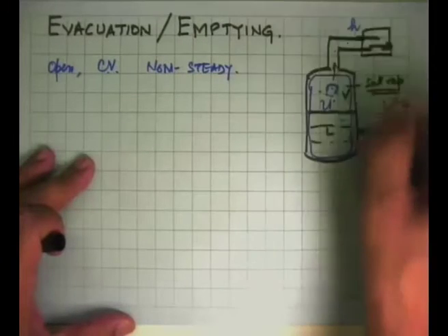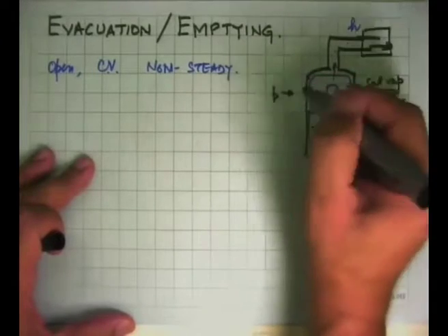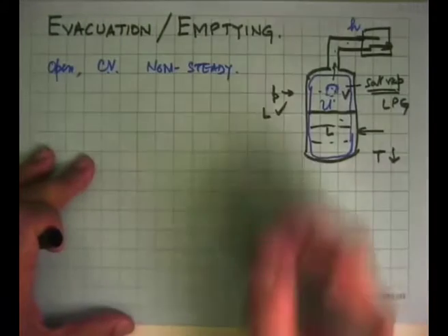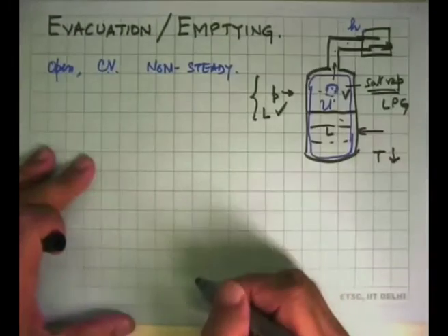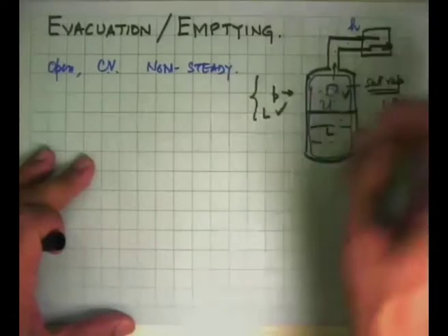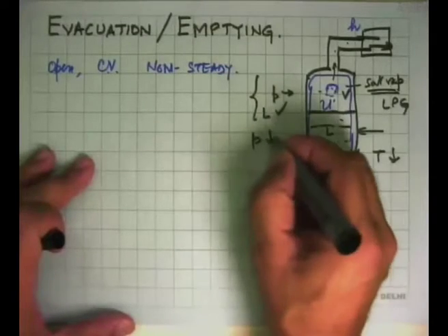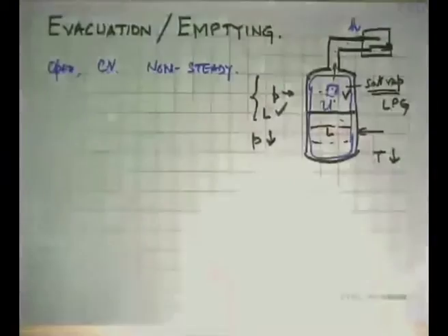The dryness fraction of the system kept going down. So inside, the supply pressure remains constant as long as there is liquid inside the cylinder. And that's the nice thing about the cylinder, and the pressure regulator is able to do its job quite nicely. Once the liquid is gone, you have dry saturated vapor, and then when you keep drawing out, there is no more liquid to evaporate, then the pressure in the cylinder begins to go down. And that's what I just mentioned, the pressure regulator then cannot do its job.